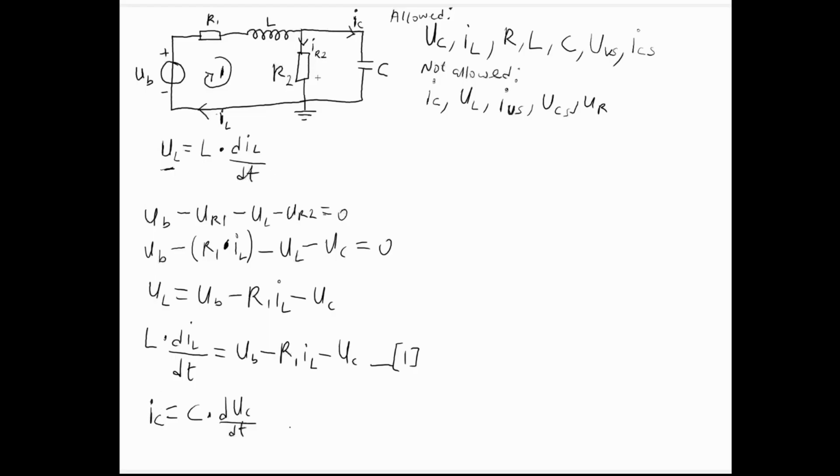So we go back to our equation. You see, this is where the capacitor is located. In the neighboring region of this capacitor, look for, and because we have current, the node voltage analysis or KCL will be very relevant here. We make our life easy. So now, the capacitor has two terminals, right? Either to this side or to this side. Look for the junction, the nearest node that you want to make use of. For me, I will use this one here at the upper side.